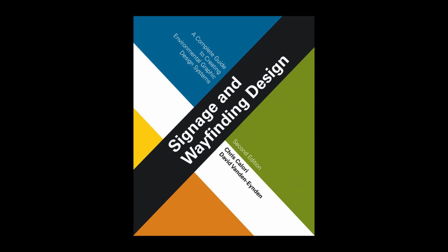Other mechanical finishes for metals include sandblasting and bead blasting, which produce a uniform blanket of pits rather than scratches in the metal surface, giving the surface a more frosted look than scratched finishes. Metal surfaces are also sometimes acid etched, which creates a finely frosted surface. Some metals are available with unique manufacturing imparted finishes, such as embossed textures, but in the sign industry, most metal finishes are imparted in the sign fabricator's shop. See figures 6.67 through 6.69.